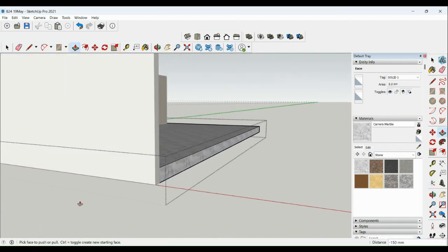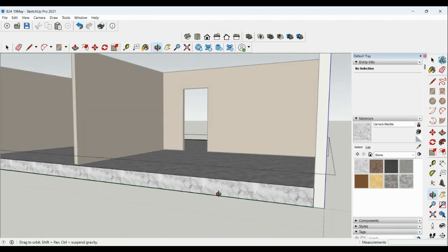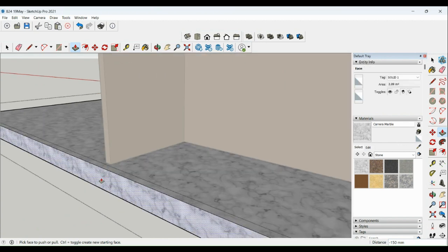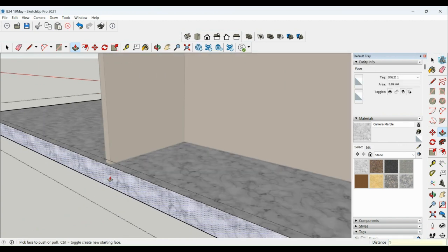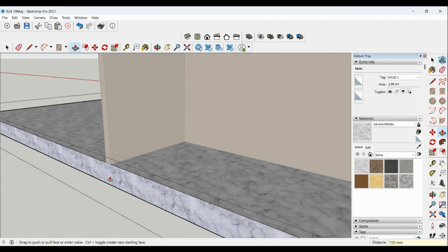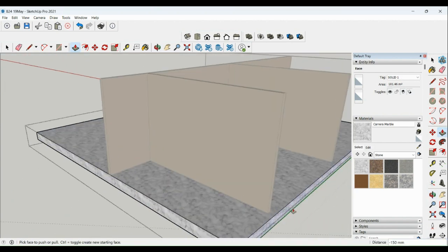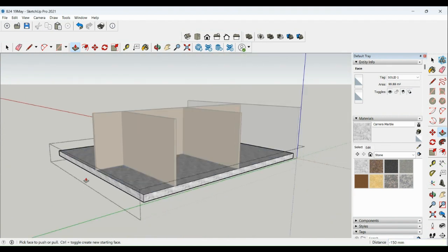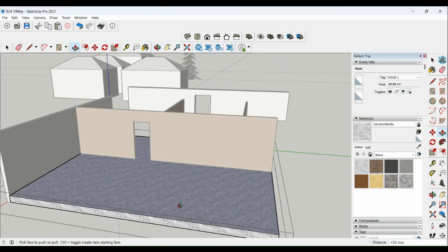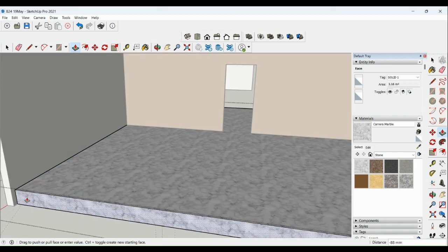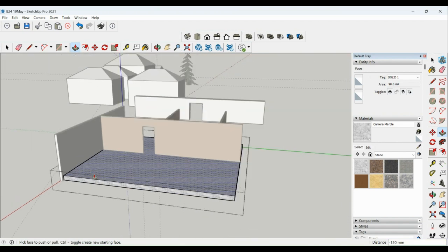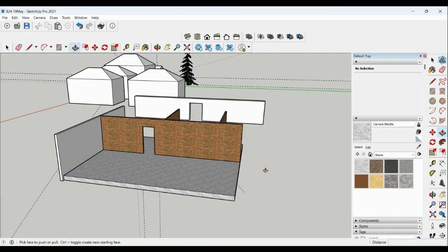So there we go. Okay, we can modify groups or solids, and also here we can just push this going in 150, enter. So it's exactly there now. We can do it on the side also, push it by 150, enter. Also on the other side. I think it's already good. Not yet. With 150, enter. So that's the way. Okay, and then close the group.